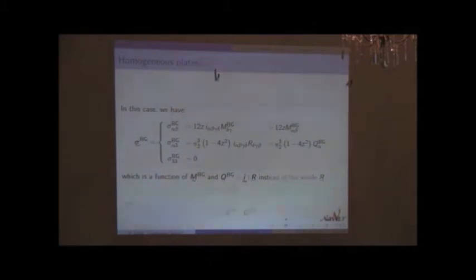All right. Just a question. Yes. This will also be what you get with homogenization, this distribution or not? Yes. You will get this, as the stress will be directly a function of the shear force, but the displacement localization related to the shear, the transverse shear warpings, is not only the shear force. It's a bit subtle. All right. So this is why you retrieve Reissner-Mindlin.